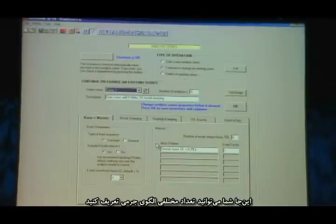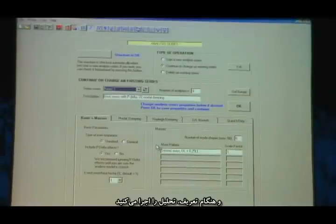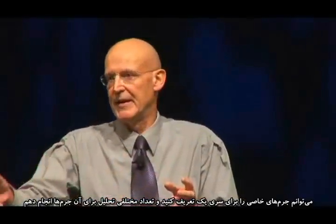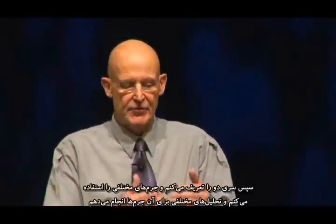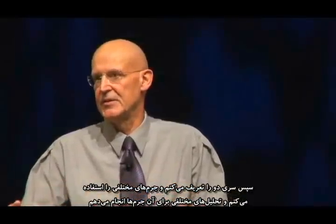What you could do is specify a number of different mass patterns, and when you come to run your analyses, you say, okay, I'll use one particular set of masses for Series 1, and I'll run a number of analyses with those masses. Then I'll create Series 2, and I'll use some different masses and run some different analyses with those masses. I don't have to create a new structure, I just have to create a new analysis series.